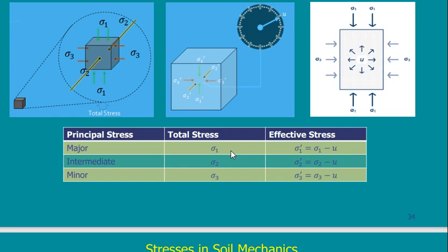If the soil was carrying 50 and 20 was going to the water, maybe after a while water will carry only 10 and soil will start to feel 60, and so on till the load carried by the water is 0 and the whole load is carried by the soil.